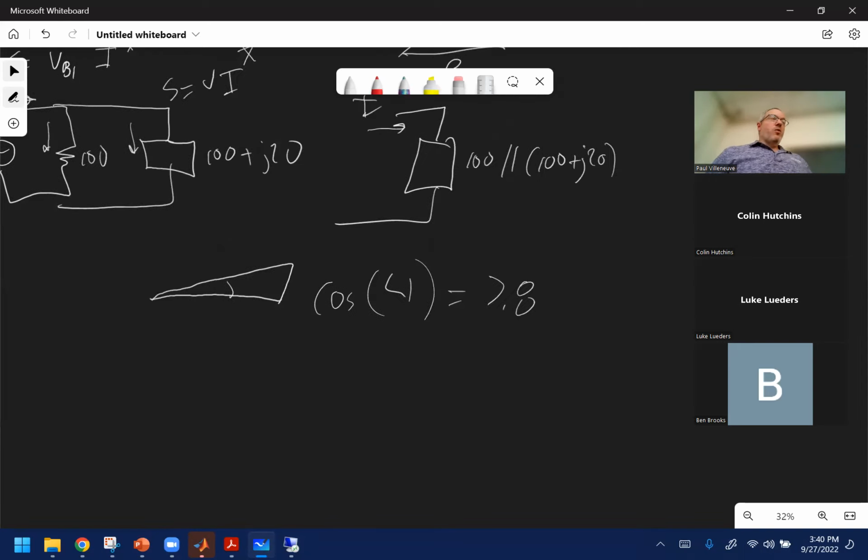So what you all were doing is you were getting a power factor of 0.9, then you said go to 0.8. What you were actually doing was pushing it to go negative in this direction. So you ended up with a power triangle where this was the cosine inverse of 0.8. You added too much capacitance, and now you made it leading, if you got the right numbers. Some people had different incorrect numbers, and if you had incorrect numbers, I tried to give you credit based on the approach that was taken.